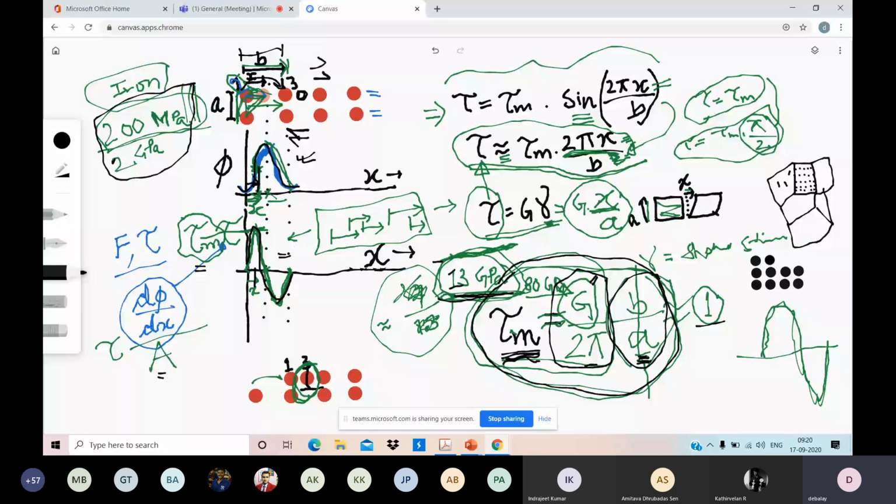There are certain methods by which you can produce defect free single crystals, which are called whiskers. So there you do not find any defect, and if you want to create defect, you may need very high stress. But in general, structural materials always contain defects in the form of vacancies and dislocations.